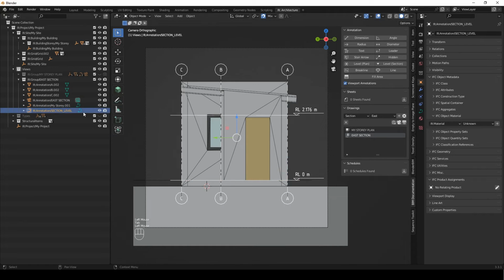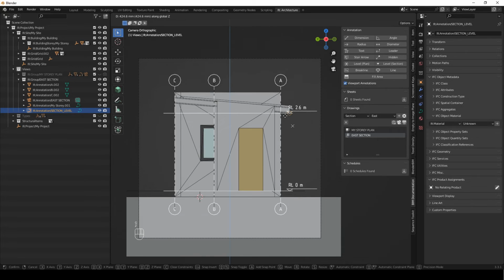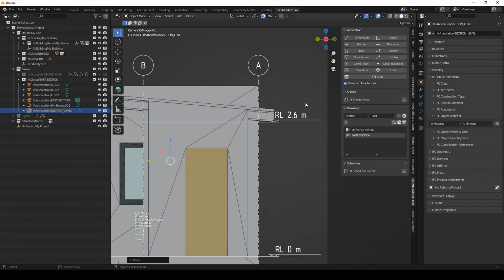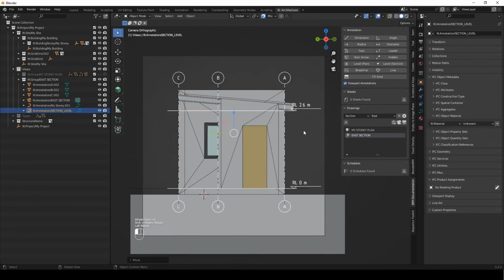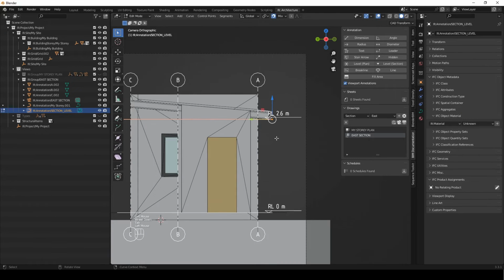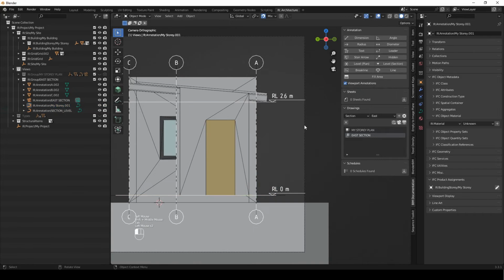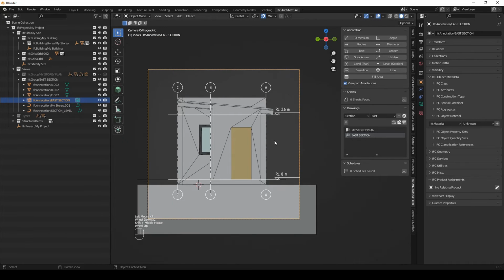And then I'm going to select the one I've just added, the section story. And then I'm just going to say GZ. And you can see it automatically updates the height of the level line. So it says 2.6. I think this is just going to overlap too much. So I'm going to select that, and I'm just going to say GY, bring it out, -150, I think. Yeah, that works fine. I'm going to select my other one, tab, GY, snap it to that one. And then I think I'm just going to adjust my camera position as well, GY. We're going to disable our snaps.